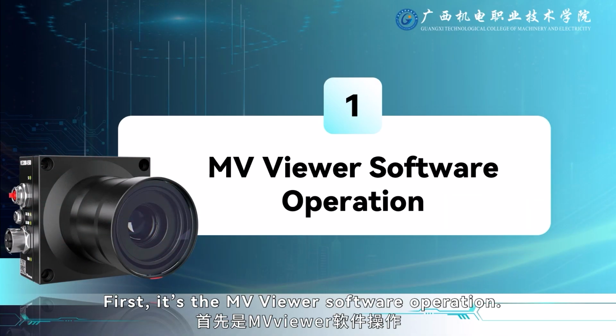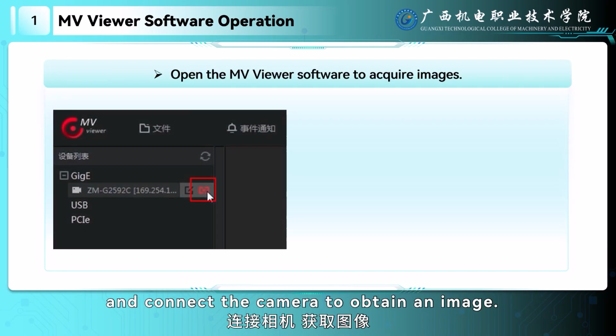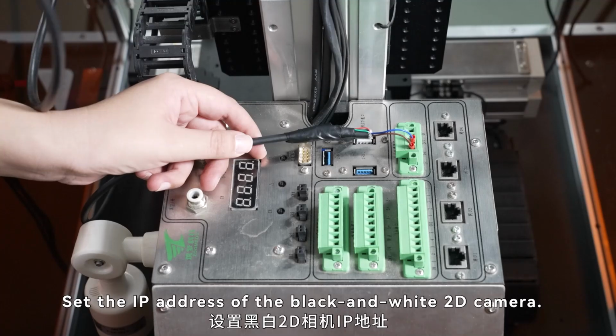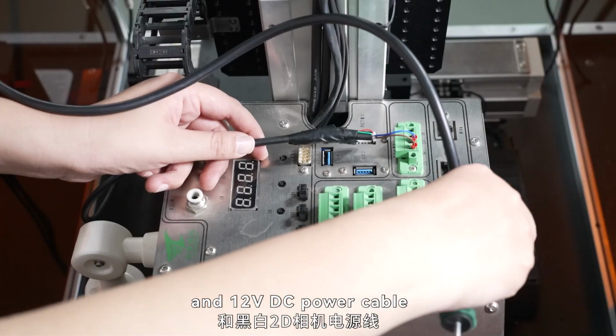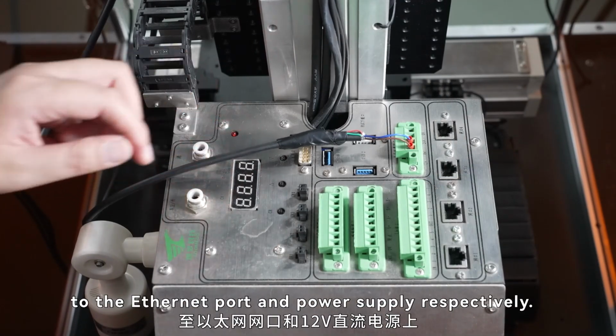First, it's the NV Viewer software operation. Open the NV Viewer software and connect the camera to obtain an image. Set the IP address of the black and white 2D camera. Connect the camera network cable and 12 volts DC power cable to the Ethernet port and power supply respectively.